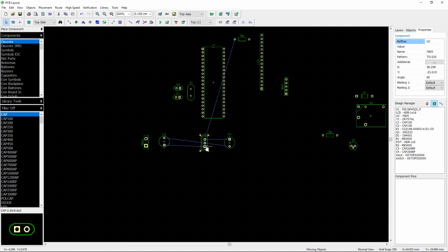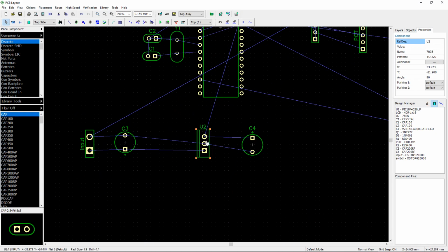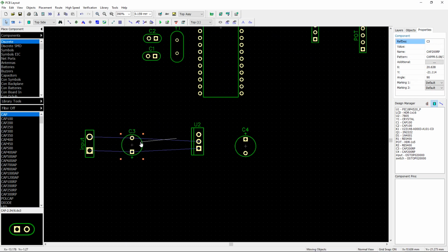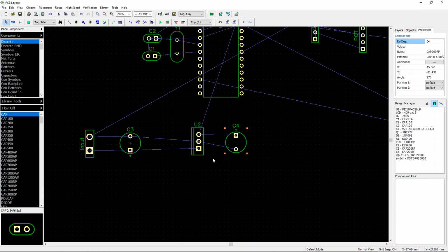So as you can see, this is the voltage regulator, and if you have noticed it physically, we have these two lines here. These two lines represent the back plate, whereby we have the ground plate, that metal flap. So when you're mounting your heatsink, you mount it right here. So that's why I'm leaving this space in case we want to mount the heatsink. Because if I have this capacitor right over here, it's going to complicate it. So I just move the capacitor right back there, and maybe this one I can move closer because nothing's going to be here.